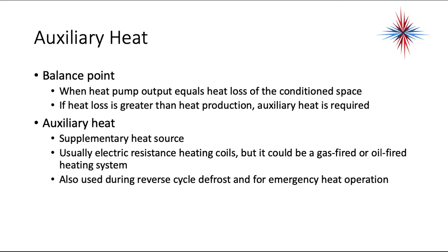Auxiliary heat is a supplemental heat source. In heat pumps, it's usually an electric resistance heating coil, but sometimes in different parts of the country, it'd be a gas-fired or oil-fired heating system. It's also used during reverse cycle defrost and for emergency heat operation.